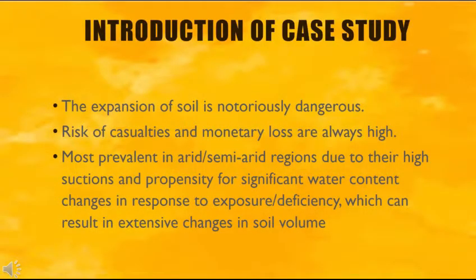The introduction of the case study is that expansive soil is notoriously dangerous. The risk of casualty and monetary loss are always high. Most prevalent in arid or semi-arid regions due to their high suction and propensity for significant water content change in response to exposure or deficiency, which can result in extensive change in soil volume.